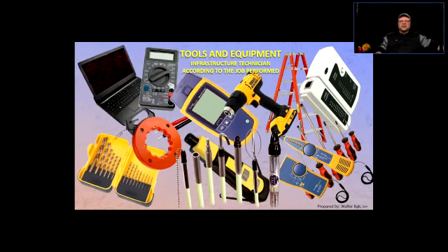Aside from the ladders, when we talk about working on heights, it's a really extremely good idea, more than a good idea. It's almost pretty much a must. You will have to arm yourself with 2 types of licensing tickets, okay? The first is the working on heights ticket. It's a plastic card. You receive training and you get the little plastic card that says you have completed the working on heights training, signed by so-and-so who did that training, okay?